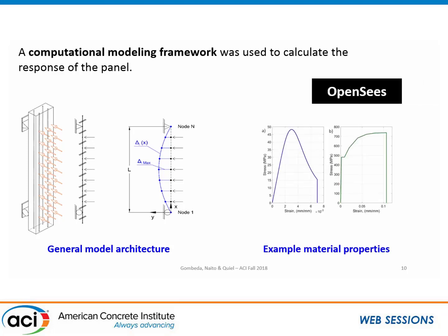And the important thing here is you can actually use expected material properties as well. Because this is a performance-based approach, and we want to incorporate what the panel will actually behave like, these things are essential. Now, you don't necessarily have to use the actual pulled stress-strain curves for rebar. It's certainly okay to some extent to use a bilinear curve where you go yield and ultimate and apply the dynamic increase factors accordingly. We've done some work with that as well. So there's some flexibility involved here at the hands of the engineer.